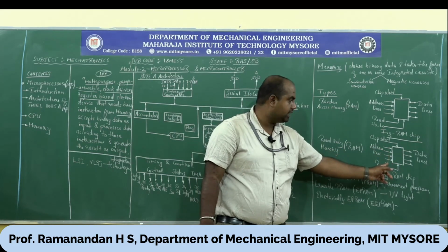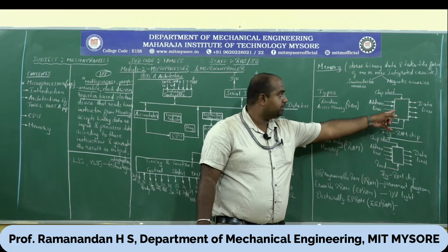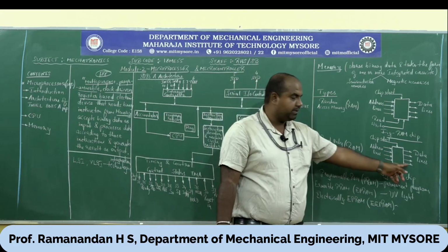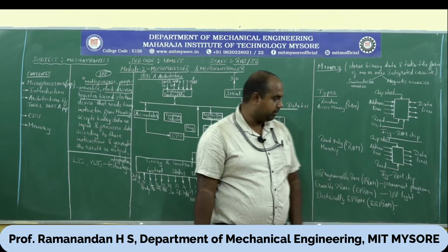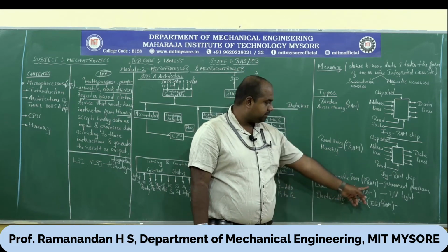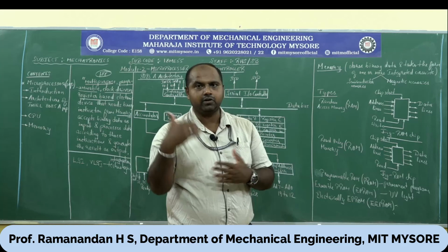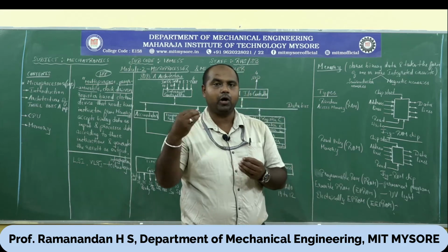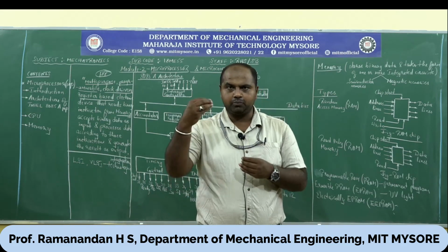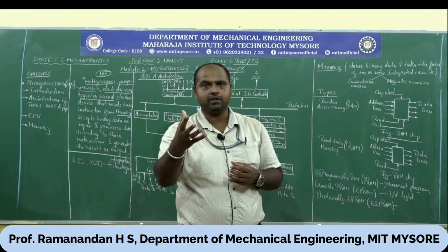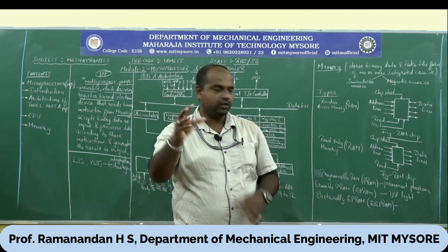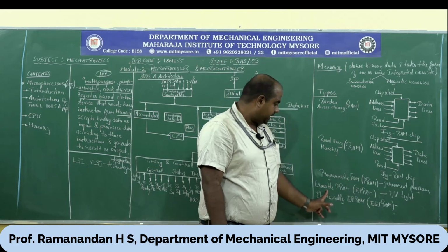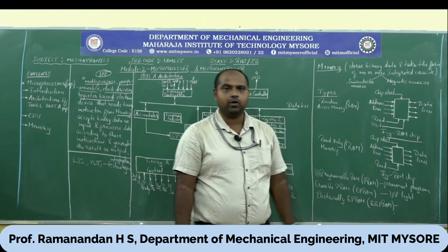That is why you can see the address line is unidirectional here. In RAM it is bidirectional: data can be read as well as fed. But here, in read-only memory, data can only be read. Similarly, you have something called PROM, programmable read-only memory, where a permanent program can be written by the user with the help of a PROM programmer. There is something called a programmer, a set of instructions or software. With the help of that, you can feed information to the ROM. That is called PROM, programmable read-only memory.